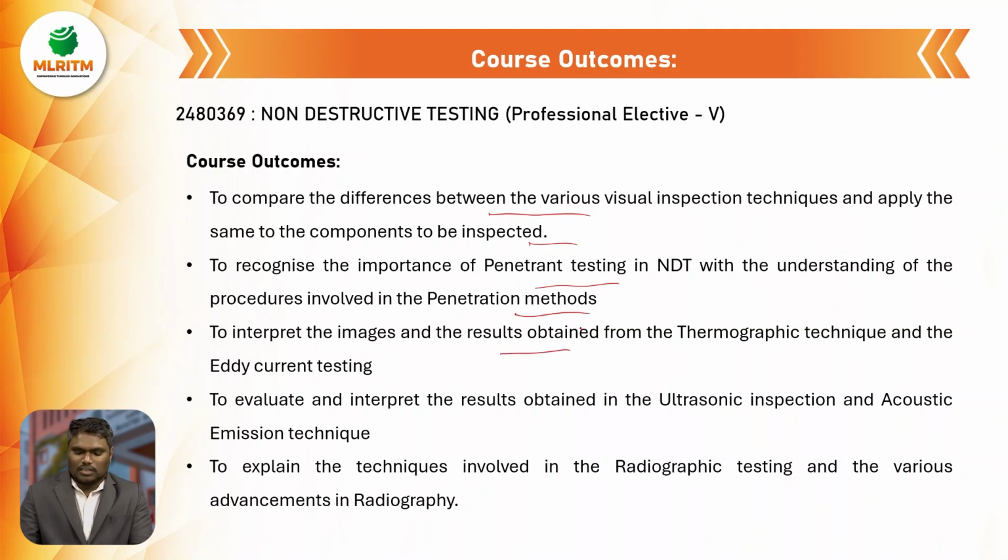To interpret the images and results obtained from thermographic technique and eddy current testing. Even from the thermographic technique, defects will be found out by passing the electrical signals due to the temperature differences. So in the eddy current and thermographic technique, the results will be obtained from them. And to evaluate and interpret the results obtained in ultrasonic inspection and acoustic emission technique. In the ultrasonic inspection, the sound waves will be sent to an object, so that where there is a defect, the sound reflection plays a major role, so that it can be detected early.